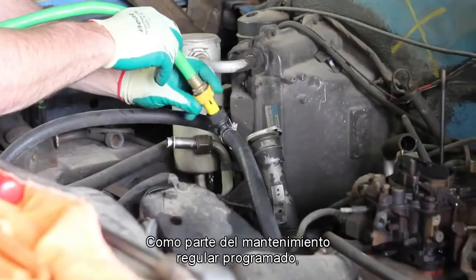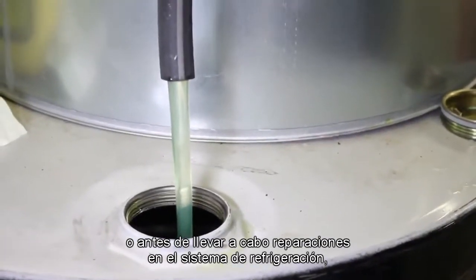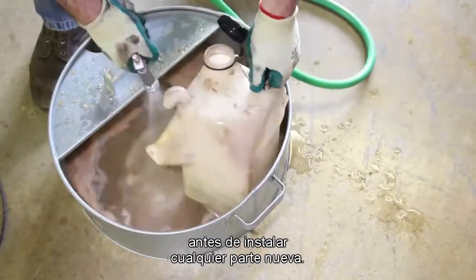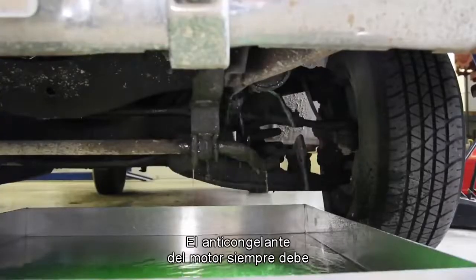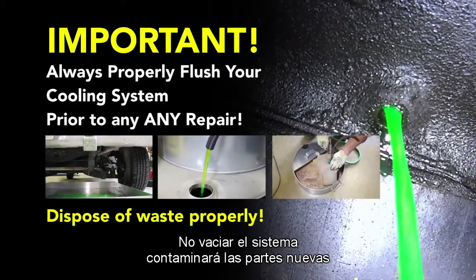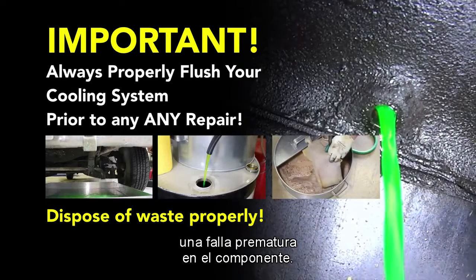As part of your regular scheduled maintenance, or before performing a cooling system repair, it is recommended to flush the cooling system prior to installing any new parts. This is a task made even easier by using a flush fill kit. Engine antifreeze should always be captured and disposed of properly. Failure to flush the system will contaminate the new parts being installed and could lead to premature component failure.